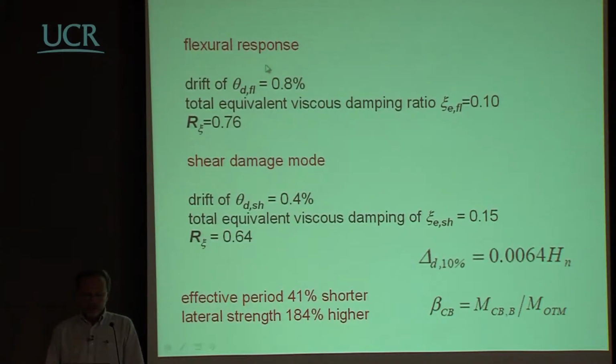So again, we check all these numbers here, and you will end up with something where you could guess what your design displacement could be. And in most cases, you will be surprised to see that you have something which is not too different from this value here, which is in the range of 0.6% of the height of the wall.